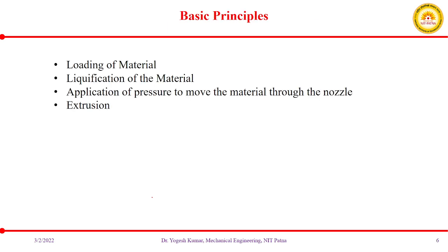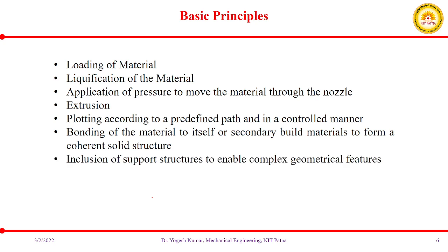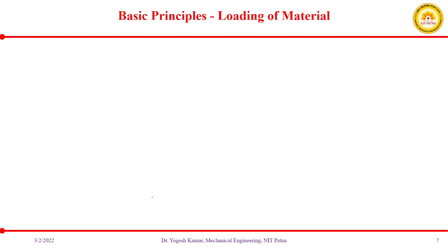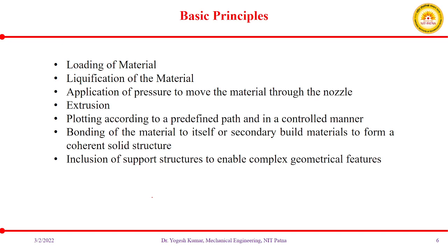Yeah. So talking about the basic principles, the main things in order to understand extrusion-based additive manufacturing processes, or you can say the basic steps, are loading of material, then liquefaction of the material, application of pressure to move the material through the nozzle, then extrusion, plotting according to a predefined path and in a controlled manner. Obviously, it is done in a sliced manner.